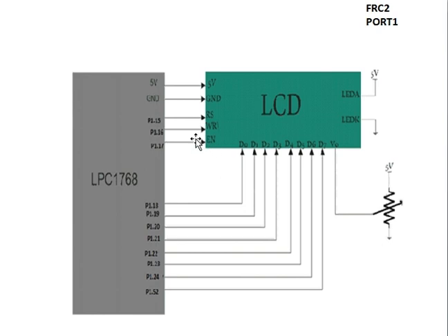So it has to provide a pulse, and since we are using write, this is to write a data command has to be written onto the LCD module. So the status of enable should be made 1. You should keep this state for a while. You have to provide a delay, then you have to trigger this low, so it becomes a falling edge of the clock. In that case the data will be transferred.